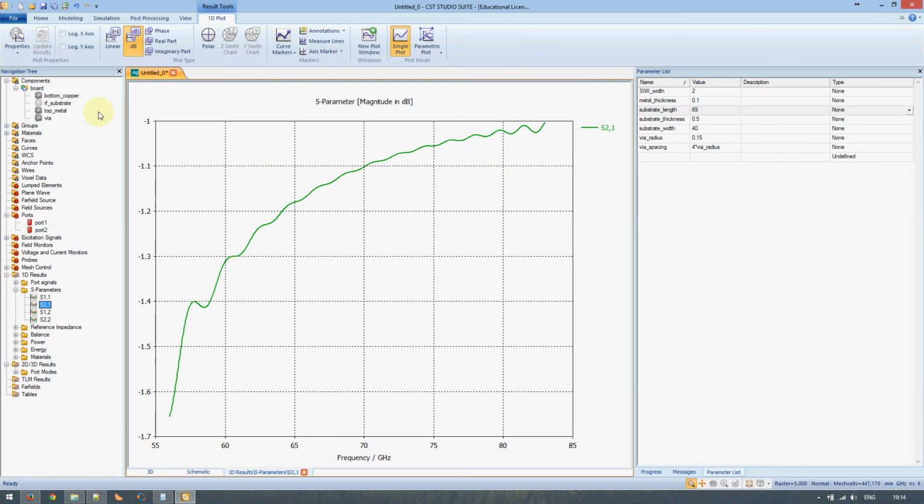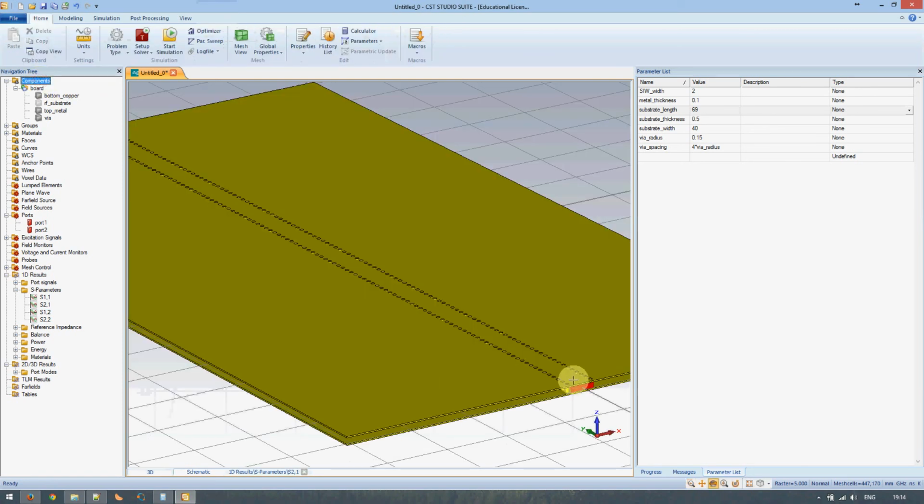In SIW, this varies according to various things, for example, the thickness of the copper, the height of the board, the dielectric constants, and the loss tangents of the board, according to relations that have been derived in the literature. And I would suggest that you go and look these up if you're planning on doing a comprehensive study. I think that is all that is needed for now.